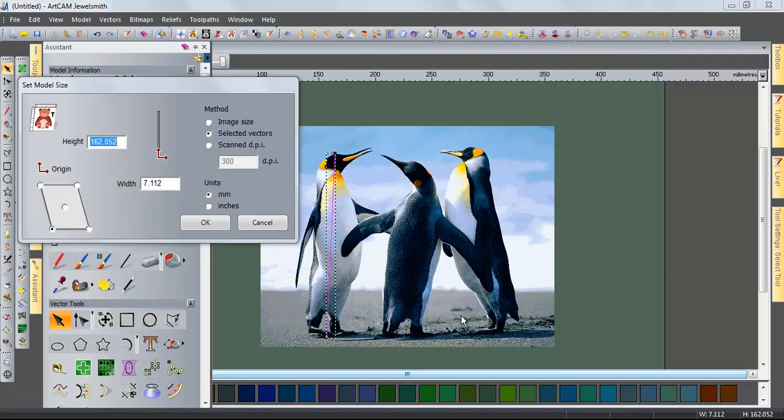In what way? For example, let's assume that the penguin's actual height is 70 centimeters. Let's say we want to create a relief on our machine, one-to-one with its actual size. What do we do with this? In order to get the 70 cm height of the penguin, it is enough to draw the line from the bottom to the top, as you have just seen in the picture, and make this line 70 cm when the select type vector is active.